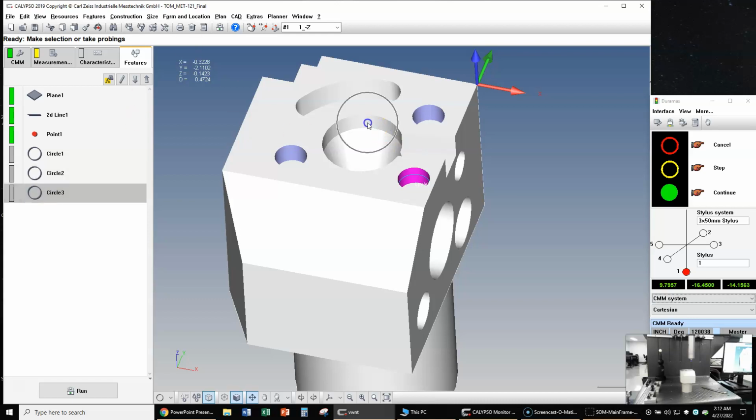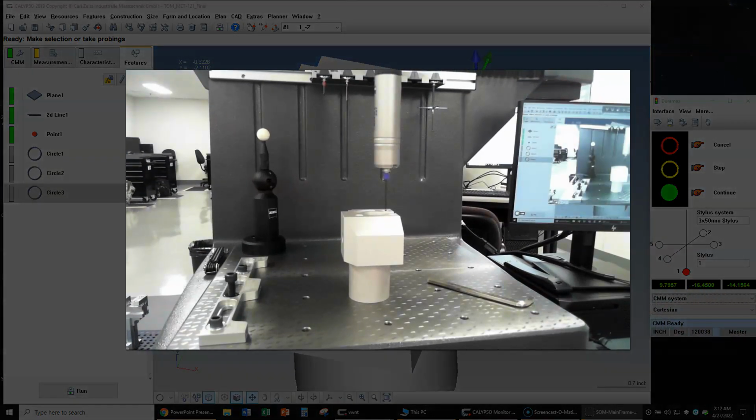For this other hole here, I'm going to touch using the probe itself. I'll go use the teach-in method for that. And that's easy too. Just make sure you're out of any command. Use the joysticks to go over and touch 7 points. The only difficult part about this is getting those 7 points to be evenly distributed.